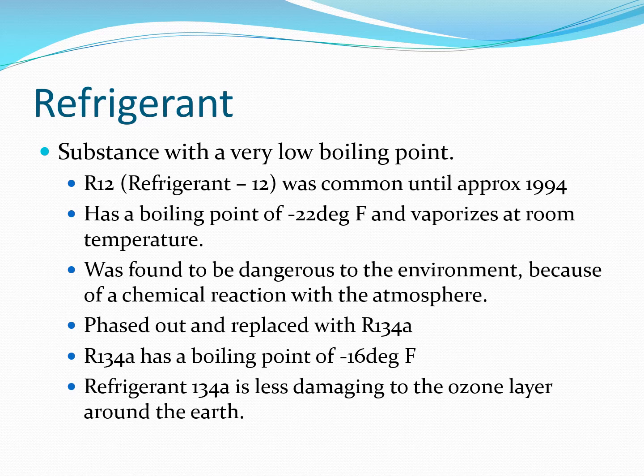R12 was phased out and replaced with R134A, somewhere around 1994, 1995. R134A has a very similar boiling point of negative 16 degrees Fahrenheit. And we're throwing numbers around here that we're not quite used to. I mean, the temperature never quite gets to that point unless you're up in Alaska or Canada. Sometimes you might get into some wind chills that are approaching that number, but this is something that's kind of foreign to us.